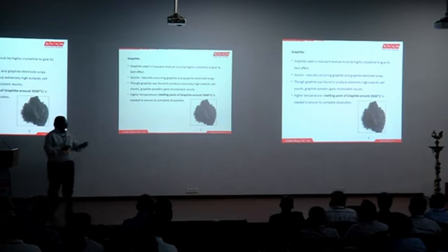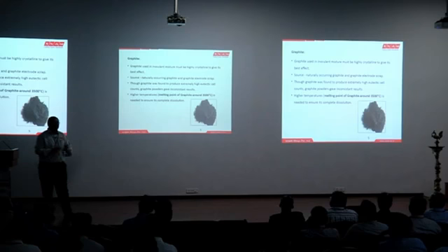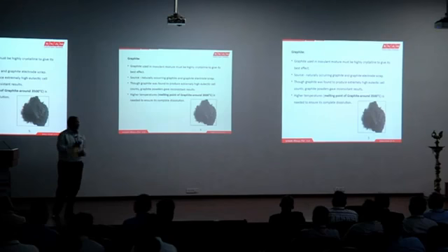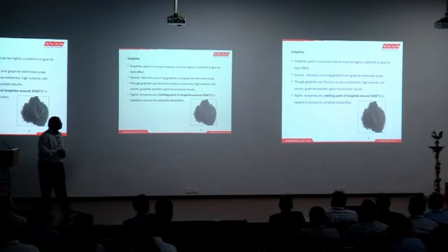Though graphite by itself is a graphite promoter or graphitizer, it gave very inconsistent results because of its varying chemical composition and impurity content. And one more thing, we operate at a temperature of around 1500 degrees Celsius, at which it does not melt or dissolve completely.